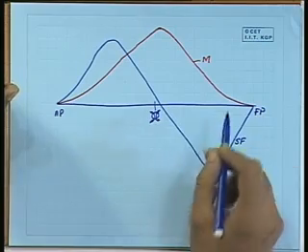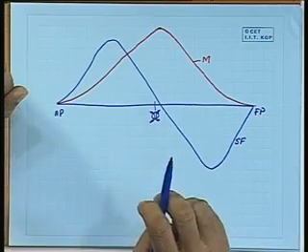So, what we have seen in the previous class was the variation of shear force and variation of bending moment along the length of the vessel. Now, the two curves which we try to draw, I have just given a small example here. SF depicts the shear force diagram and M curve depicts the bending moment diagram.